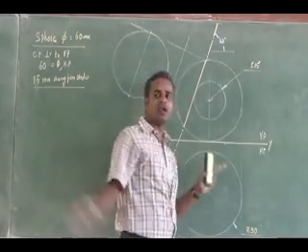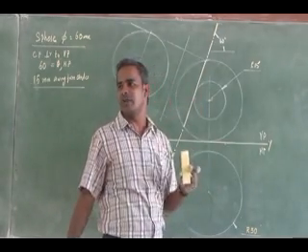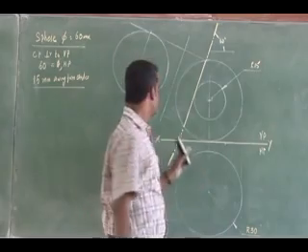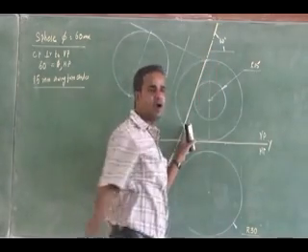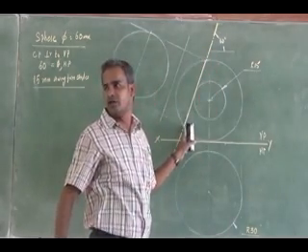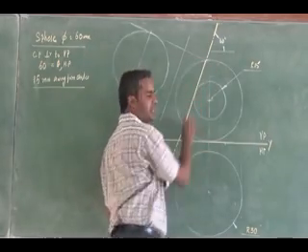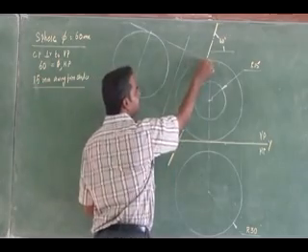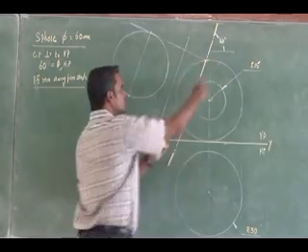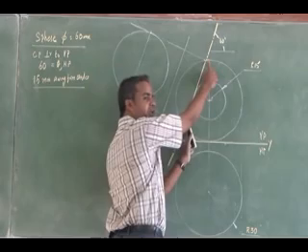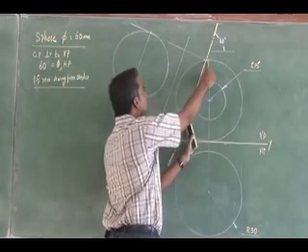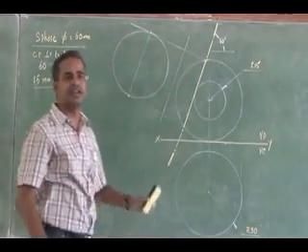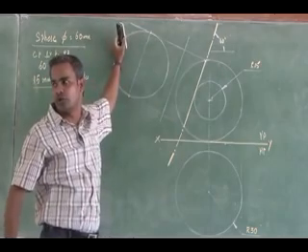The diameter of the true shape circle will be the distance between the end cutting points of the cutting plane. The cutting plane cuts the sphere here and here. So this is the diameter of my true shape circle. So I can go straight away for my true shape.